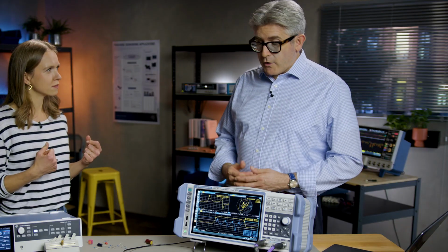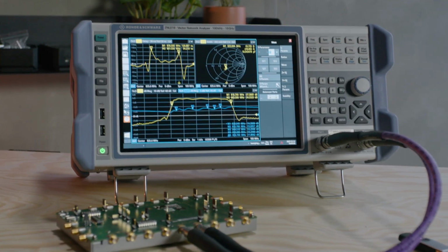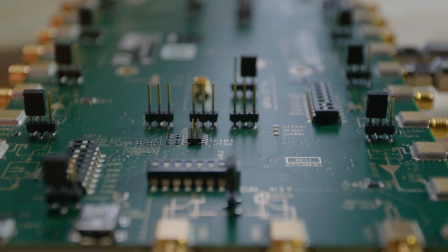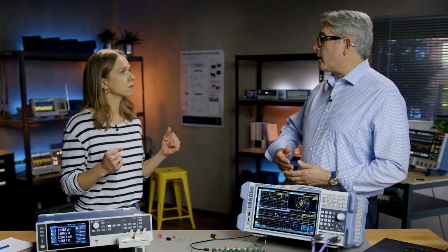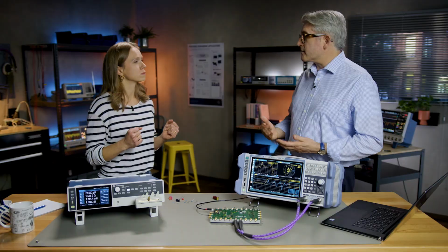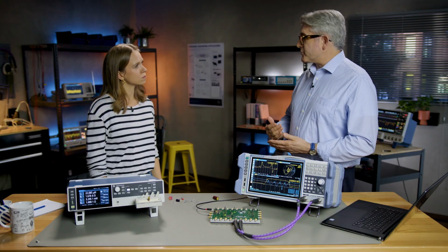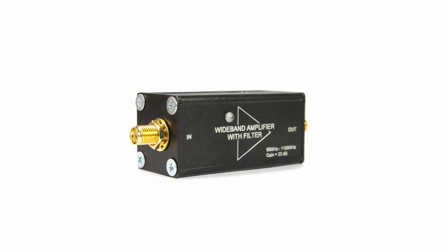With the VNA, you can characterize components wherever it's important to measure magnitude or phase, or where input-output comparisons are important. So VNAs are good for a wide frequency range. That's right. They start at the kilohertz, but they can go right up into the many hundreds of gigahertz on the high-end devices. They can be used to measure parameters over the full frequency sweep, and you can measure passive components such as couplers and antennas, or active components such as amplifiers and transmitters.